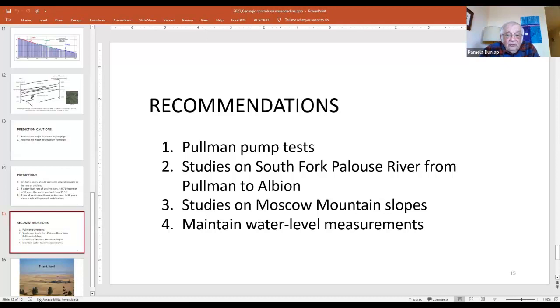The second reason is that those observation wells, those water level measurements, are the early warning system for how the model is working. Did 2 dry summers influence the amount of water decline? Did 2 consecutive years of increasing the pumping affect the water decline? You need to know that. You need to keep track of that. So that's my recommendation. It's something most solid.